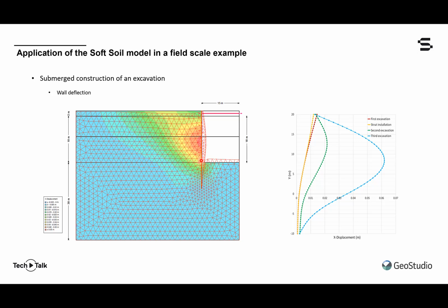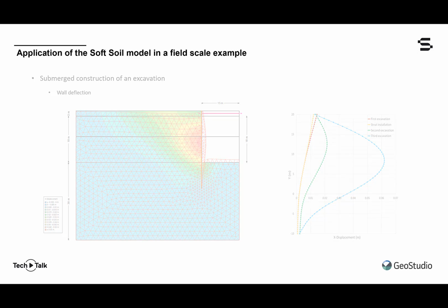So here's the exposed portion of the wall, and that would be below mid height. And again, that's confirmed by the coordinate of the maximum deflection over in Draw Graph. So again, we can see the radiating X displacements around that point of maximum deflection.